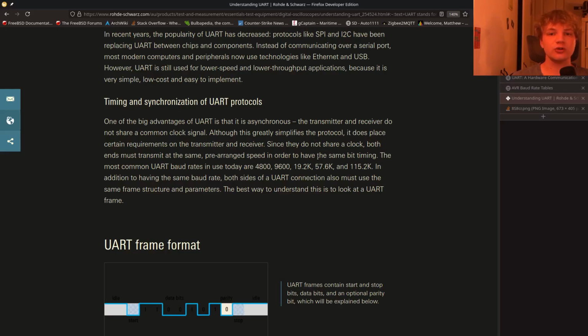And what that'll do for you is that you'll have a UART communication that shows up as a COM serial port on a Windows machine or a TTY on a Linux box that you can then get your MCU to send debug information to, or you can write data to the MCU while you're testing things. It's really, really useful, and you can do that all from a regular PC. But anyway, baud rate, that's essential for each MCU to know when to actually sample the information the other is sending. And it's just predetermined, you program it in.